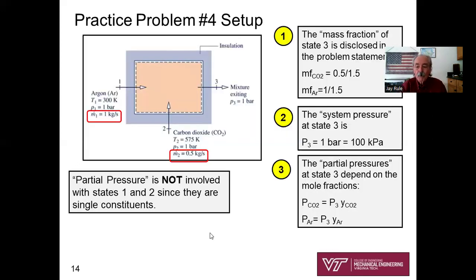Let's talk a little bit more about state 3. How will you handle state 3? Well, let's see. Can you figure out the mass fraction at state 3? I think you can from the given information and your common sense and your experience so far with steady state, steady flow, continuity equation. What's the mass flow rate at state 3? It's 1.5 kilograms per second by observation.